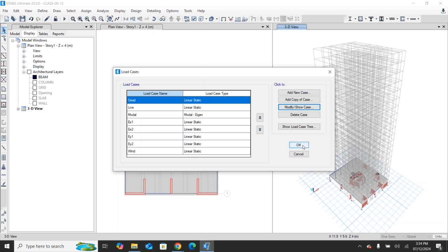Next, what we need to define is the mass. When you do seismic calculations, seismic analysis, you have to define your mass. You remember the previous exercise, we did the mass participation ratio report, everything we selected. So first you need to define your mass. Normally, as the name indicates, that is the self weight plus the live load, correct, right? So that means the DL plus LL will come. Yes. That is normally what we consider to be the mass.